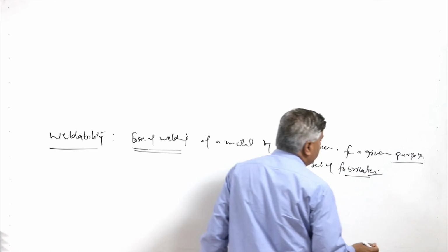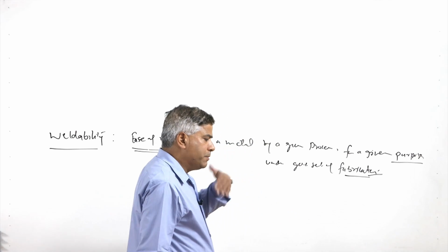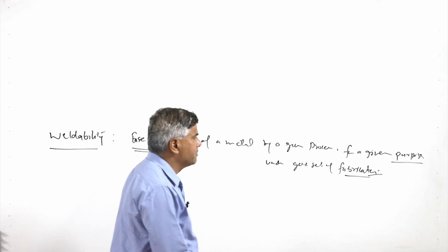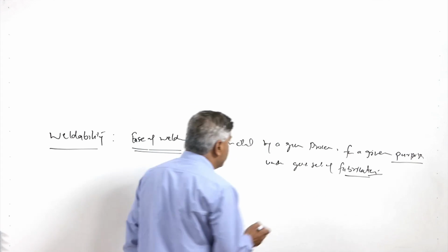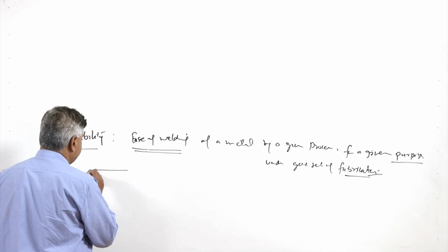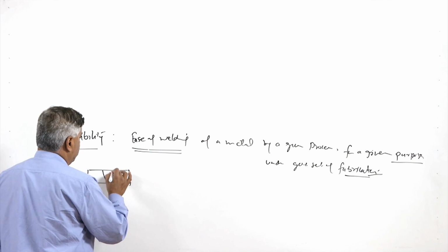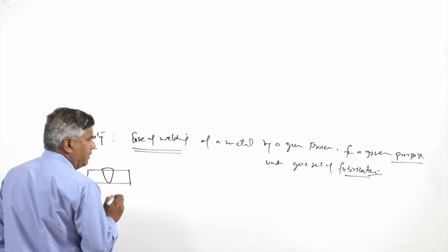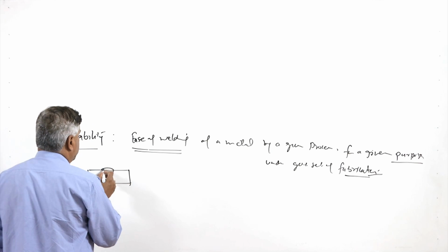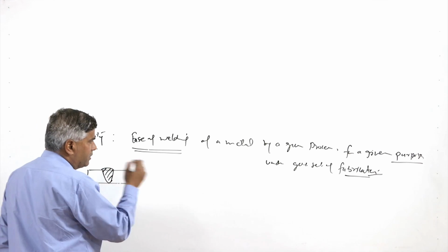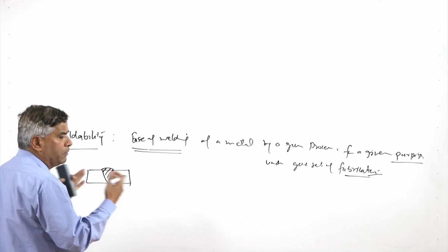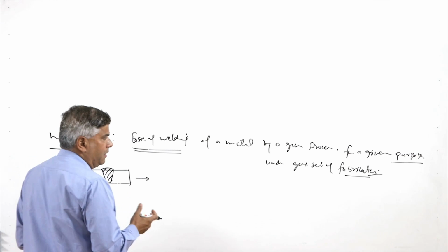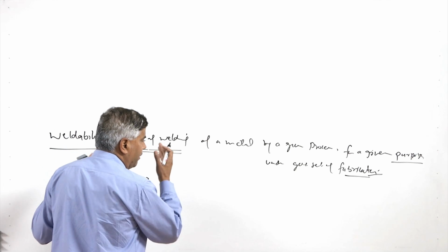The change of purpose also means the performance of the weld joint at high temperature and low temperature may be completely different from what is normally observed at room temperature. So, even despite having a weld joint which is very sound and has the required metallurgical continuity, with the change of purpose the joint may not be able to perform successfully. That will adversely affect the weldability of the metal.